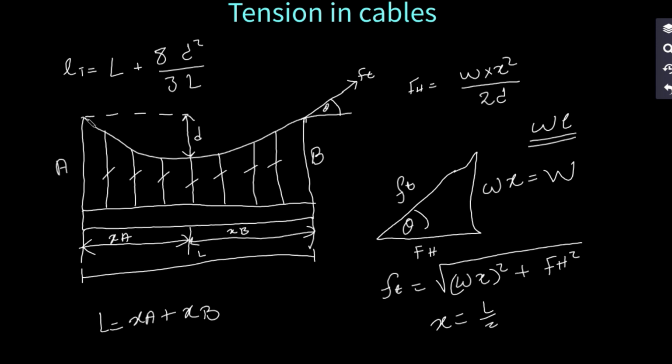We know the maximum tension will be found at the top of the towers. Since they are equal in height, we can just use one side to calculate everything. But as we have already seen from the previous lesson, whenever we have different heights on the towers, then you have to consider them both and do calculations for each one.